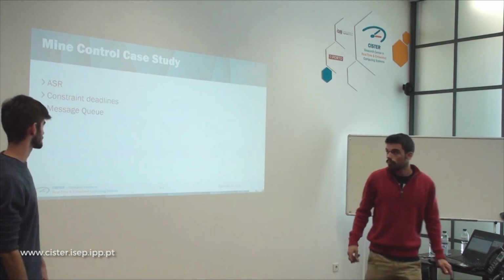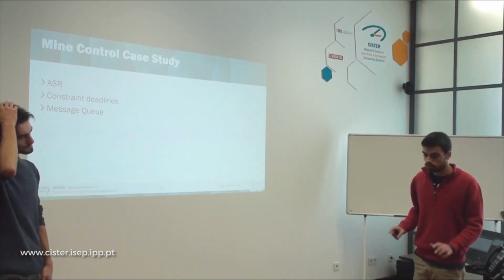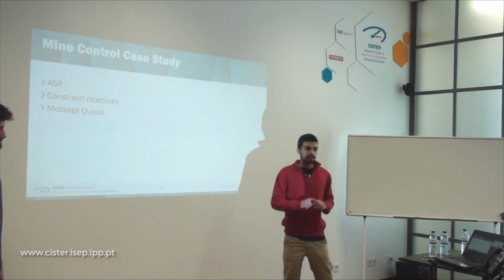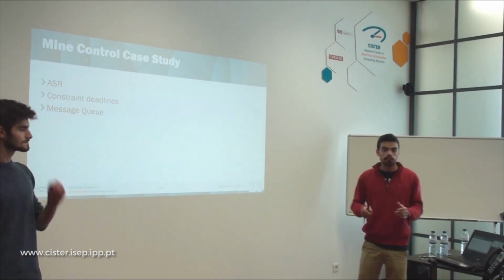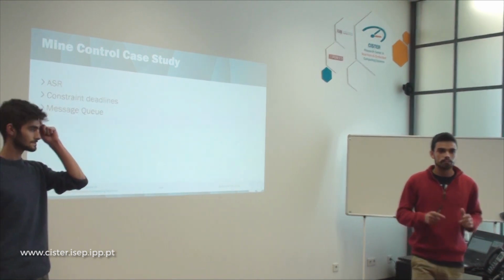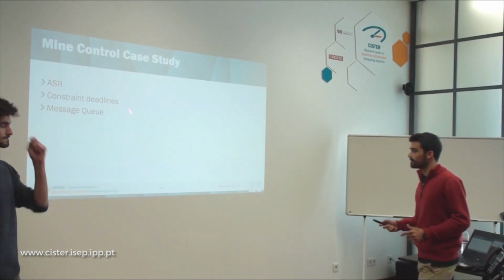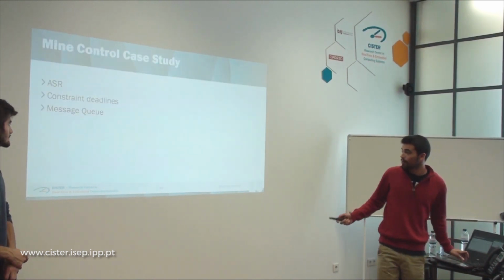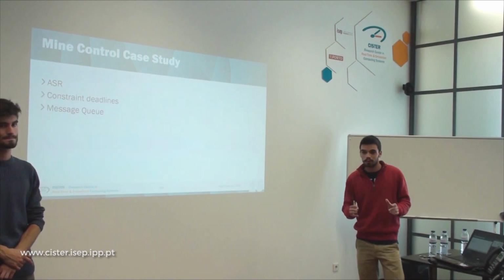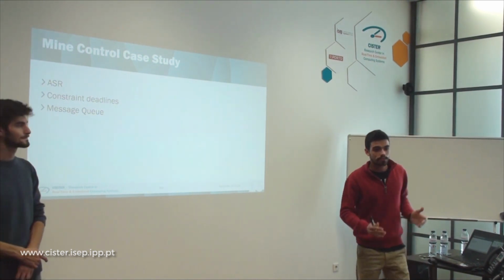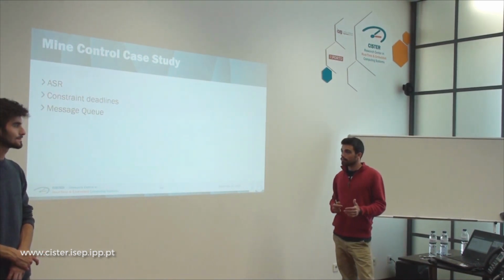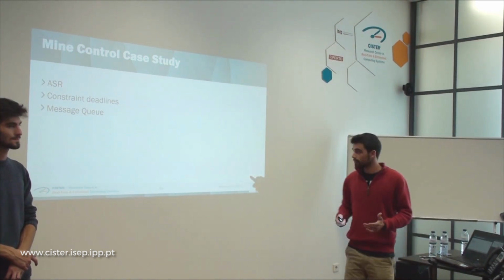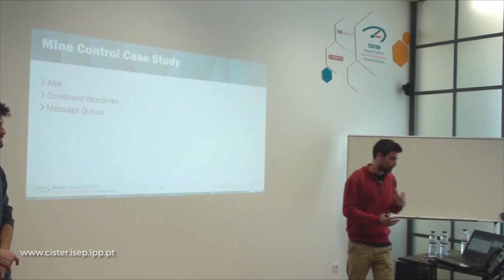With the implementation of our system, we reached 3 points. The first one I will speak about is constrained deadlines. RTEMS does not offer constrained deadlines. It only has implicit deadlines. So how did we turn around this problem? We decided to use timers to alert us and to stop the application when deadlines were missed. That was our way to turn around that problem.